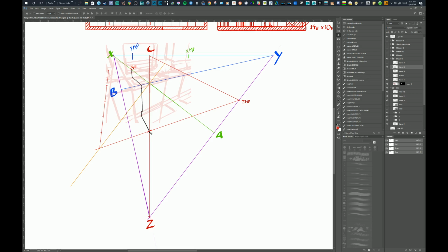Remember, this right here is 5 units high. So from the center of vision down to here is 5 units. And so that means from the center of vision along the distance line here, the true height line, to where it foreshortened or forelengthened, that 5th unit, that is going to be what needs to be divided into 5 equal units. So now I will take this 5th unit, I will go through the center of vision.